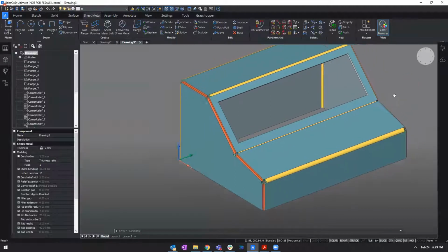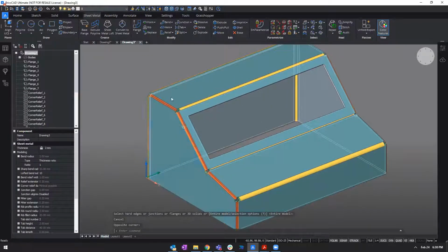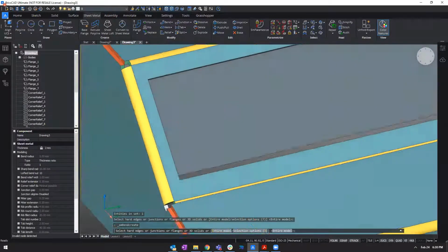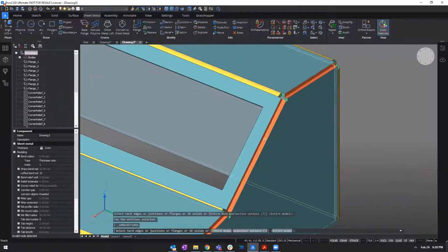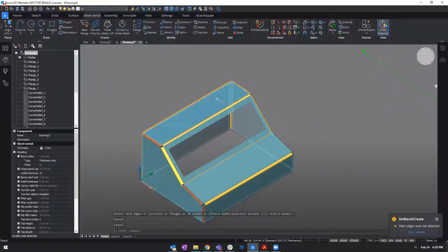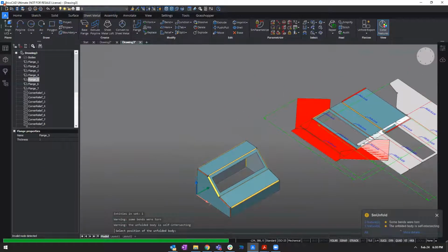So I can either do this manually, so clicking a point here, and it will create this split for me automatically. Or I can use the split propagate command, smart split propagate, where it asks me to choose a location, for example here, and it will automatically find similar locations where it can create the split. So this is actually based on a propagate command in the BIM workspace that we will cover next week. But it's a sort of smart suggestion tool where you can apply the same logic. So I will accept this suggestion. So these 4 splits here, I'll press enter.